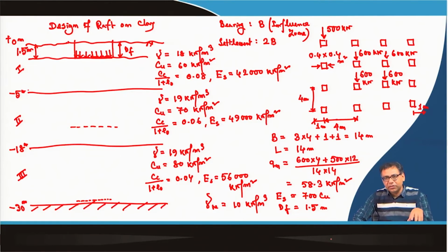Okay. So, you can see that the theory that I have discussed is for a 2 layer soil. Even for this 3 layer system you can convert it to a 2 layer system. That is not a problem, because if your bottom layers are very soft, you can take the weighted average for the bottom layers and make one soft bottom layer, and for the stronger layers on top you can take the weighted average and make it 2 layers.